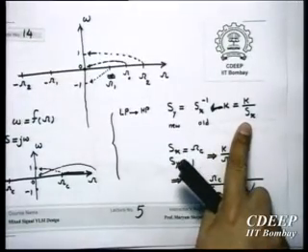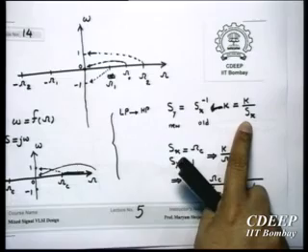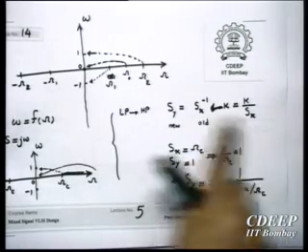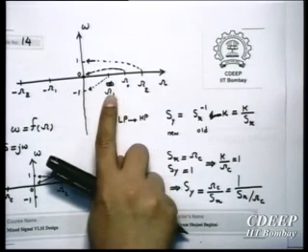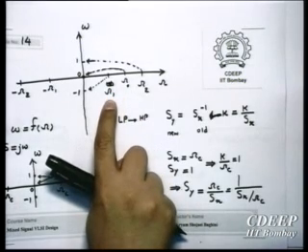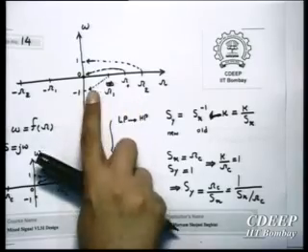Now, in the case of band pass, as I said, it cannot be just a simple function of the first order variable. The reason is that I have two values. So, I can ignore omega 0 and ask what the proper conversion is: omega 1 to minus 1 and omega 2 to 1.